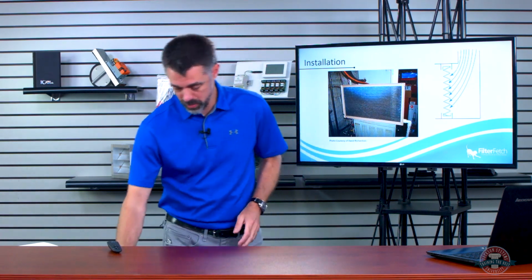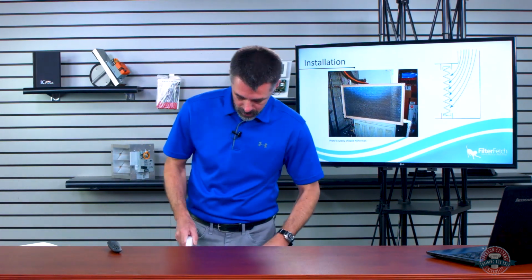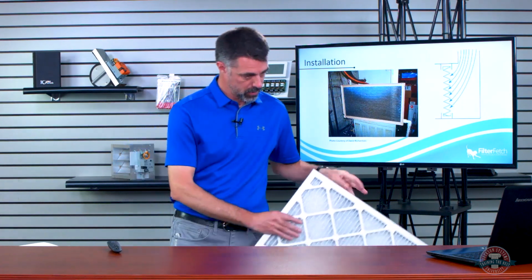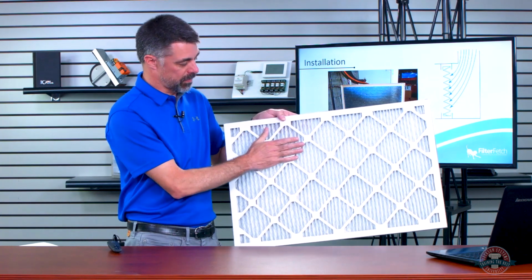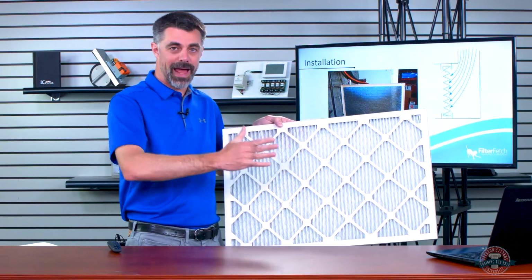We like questions. All right, Jess wants to know what happens exactly if a homeowner puts in the air filter backwards, like against the airflow, upside down or wrong way. Well, so a couple things can happen. One, it's going to filter something. However, when you put filters in correctly, we've got a metal mesh typically on the back side of that filter to keep the filter from collapsing out.